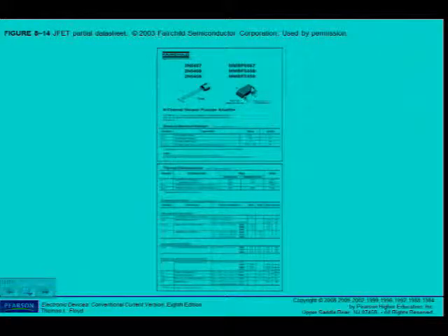So if I ask you a question and I say find for this device the typical value of IDSS, then you must read that value, not the minimum, not the maximum, unless of course I told you the minimum or the maximum. Or in the case of VGS off, I will ask you for the maximum value. So make sure about the values that you have to read from the data sheet.